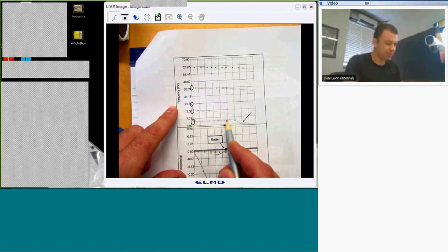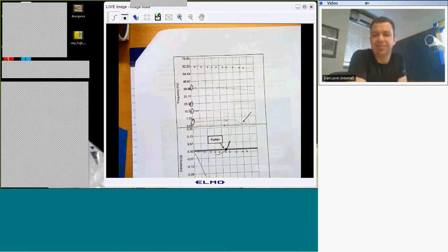Okay. So it isn't necessarily the lowest mode. Yeah, it's the second. But again, that's a flutter condition. It's really a linear combination, and I think in this particular case, it's going to be first bending and first torsion. Both are significant. Yes, the other modes are less so. Okay, thank you.